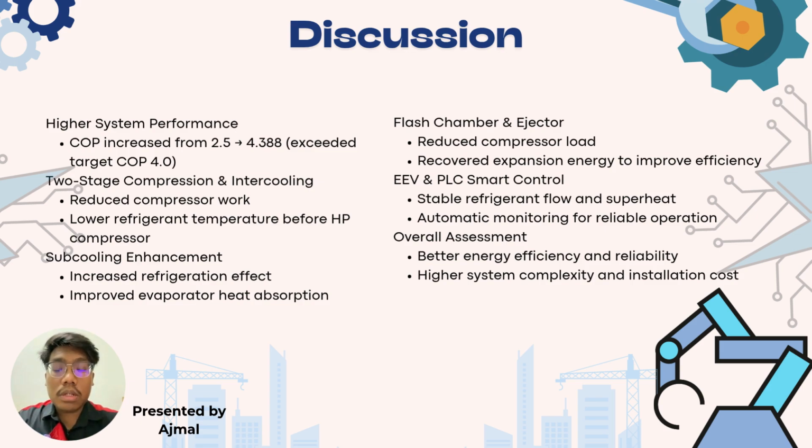Now we move to discussion. So this slide discusses the overall performance of our proposed refrigeration system. First, the proposed design achieved a coefficient of performance, or COP, of 4.388, which is significantly higher than the conventional system with a COP of 2.5. This means the system can provide the same cooling effect while consuming less energy, making it more energy efficient.